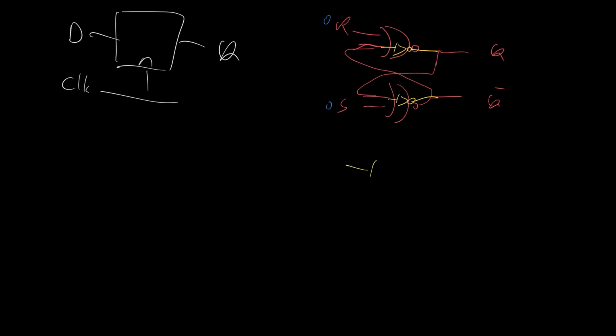And so we end up with, if I unravel them, this circuit here. And this is what gives us memory, because if the output is currently a logic 0, then 0 comes around here, it becomes a logic 1, it becomes a logic 0. Self-reinforcing, it can remember logic 0. It can also remember logic 1. If this is a 1, then 1 comes around here, logic 0, logic 1, self-reinforcing. So we have 2 stable equilibria. Either I have 0 coming out and it stays 0, or I have 1 coming out and it stays 1.